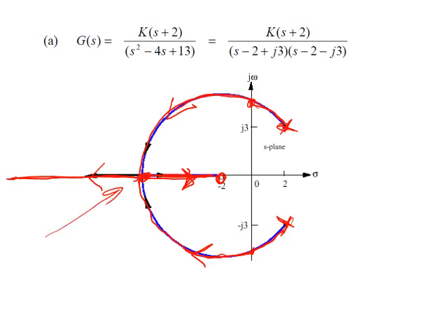So you will calculate the break-in. Once you find the break-in, that means you are going to go toward it. Now when the two poles reach the break-in, one of them will go to the zero and the other will go to infinity. That's how we can draw the root locus for this kind of pole plot. Let us continue now with the other quantities required.